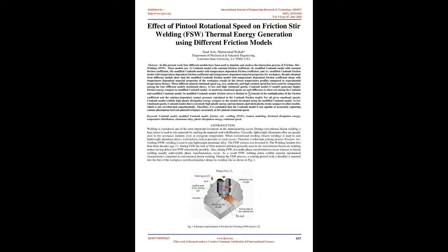Results obtained from different models show that the modified Coulomb friction model with temperature-dependent friction coefficient along with temperature-dependent material properties of the workpiece results in the closest temperature profiles compared to experimental temperature history. 3 different Pintool rotational speeds, e.g., low, moderate, and high rotation speed, have been used for comparison among the 4